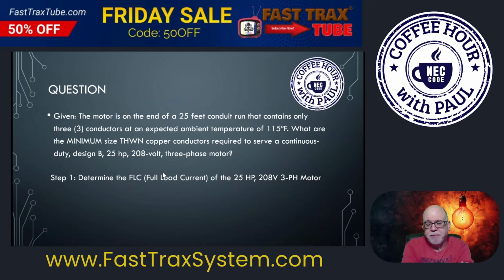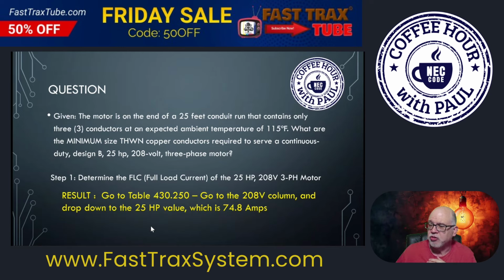So the very first step we should do, before we even get into the ambient, is to find the full load current. In order to find the full load current, the first thing you're going to do is go to your National Electrical Code and go back to the tables. In this case, you're going to go to 430.250 because it is a three-phase motor. You're going to go to the 208 volt column and drop down to the 25 horsepower value, and you're going to see that it is 74.8 amps.